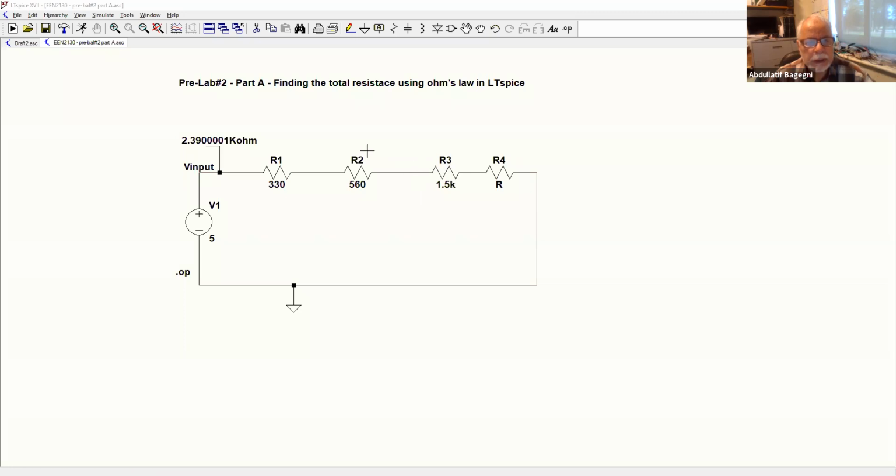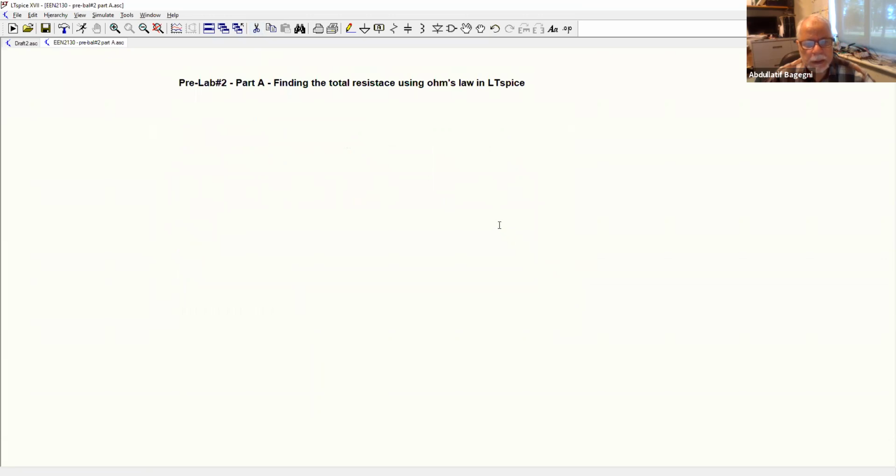I'm going to delete the whole circuit by clicking on the scissor, holding left click, boxing, and releasing. Right click to get rid of the scissor. Now we go and pick the resistance R1. Free your hand from the mouse, Control R, and place it with a left click. If we keep adding, left click, and if we want to stop or delete R3, we just right click.